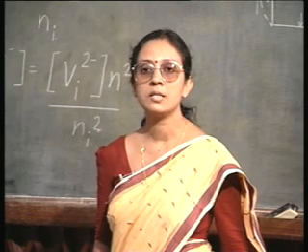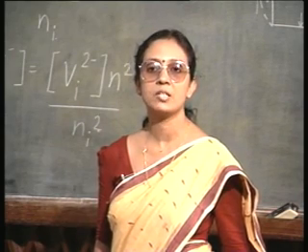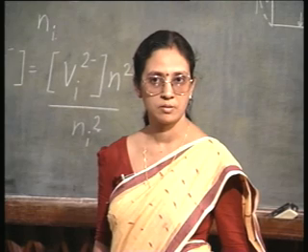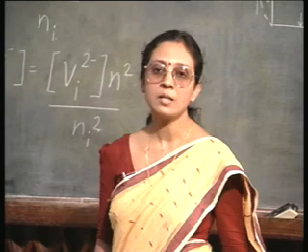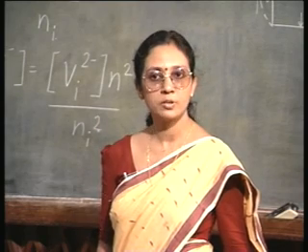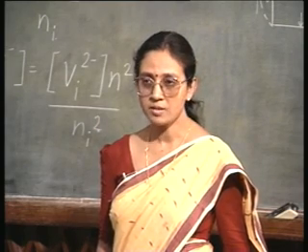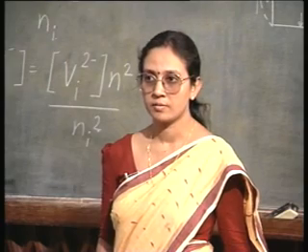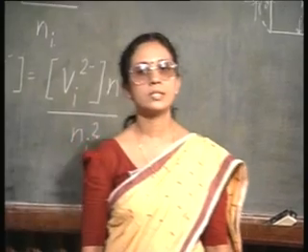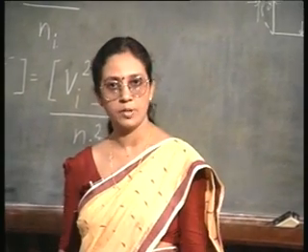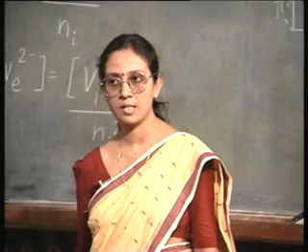Now you know silicon has a great affinity for oxygen. Therefore, the reaction product will be the release of the dopant atom and silicon dioxide. So, most cases this diffusion is carried out in the oxidizing ambient.